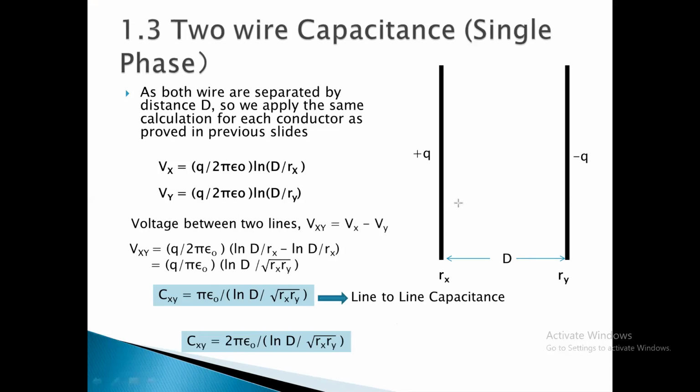So for example, here, you know that the capacitance, the voltage exactly in the middle point here will be 0, because here is the negative side and it is the positive side. So the voltage exactly in the middle will be 0. I can consider the voltage where it is 0 as neutral, N. Okay. So if it is N, then there will be 2 capacitances.